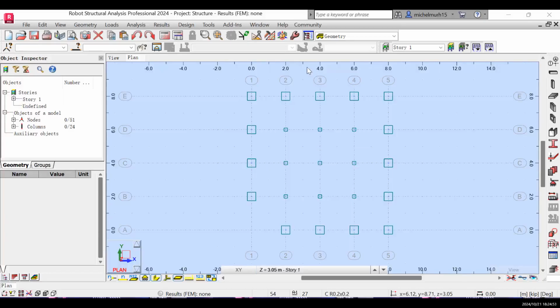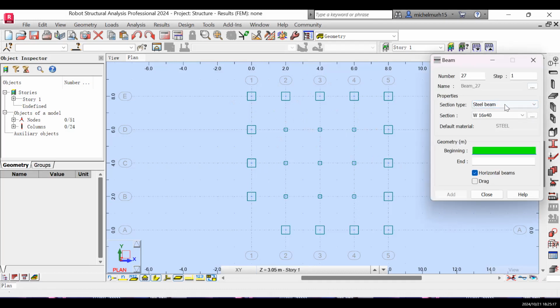and then after that, I'm gonna repeat the same process for the beam. So the beam is the horizontal element that is supported by the columns, and also it supports the floor and other elements, right? So what I'm gonna do here, I'm gonna go again on beam here. Instead of going to the columns, I'm gonna pick the element here, beam, and I'll repeat the same thing. I'm gonna change the section type to the reinforced concrete type, and for the section, I'm gonna decrease the section by tapping on the three dots here, and